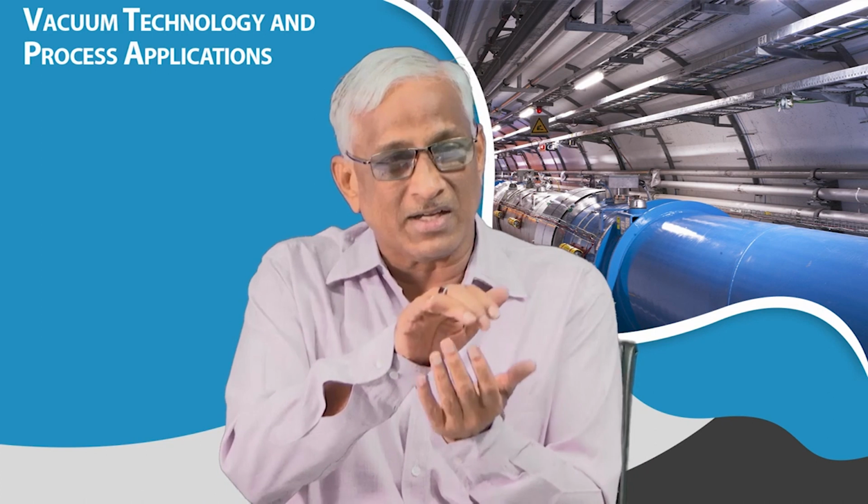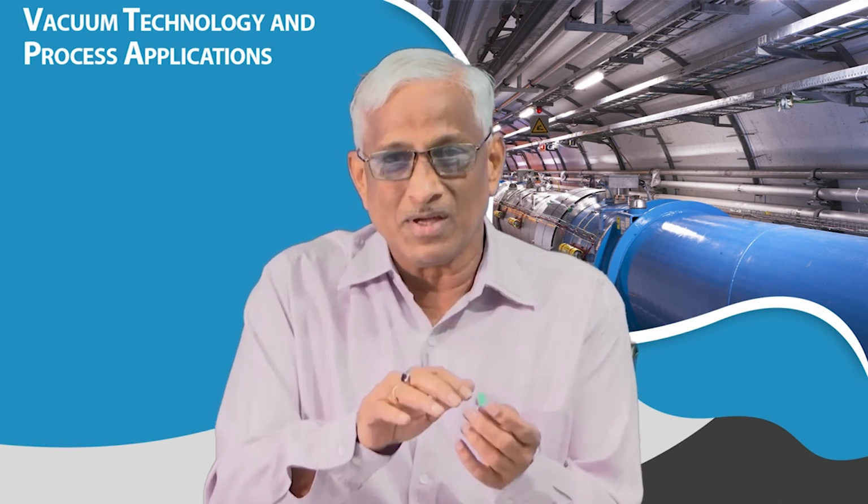So, while doing that, if you make a mistake in the conductance of the pipe, instead of 10 minutes, it will take 2 hours to get the evacuation. And at times in big space simulation chambers, if you make a mistake in the interconnecting pipe, you will end up getting 3 days, 4 days to get an acceptable vacuum before you do some simulation experiments of a satellite in a big chamber.